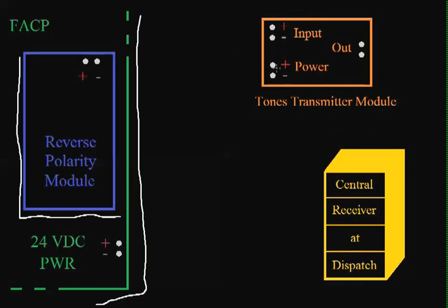So let's wire this module up. What happens exactly? Well, it needs power, just like the last thing did. So we're going to take our 24 volts off our panel. This again would be non-resettable power because we don't want it to drop out if we hit reset.